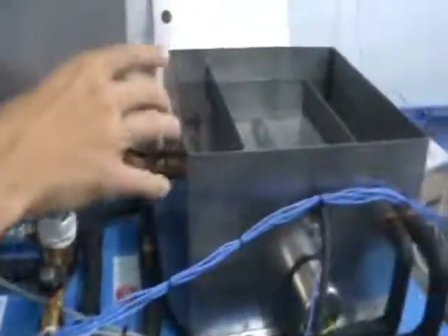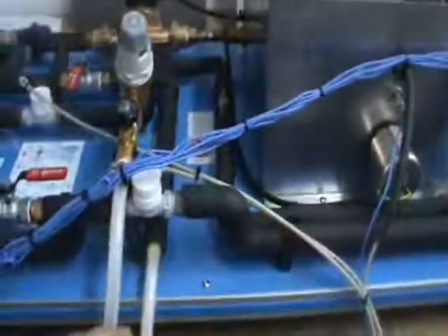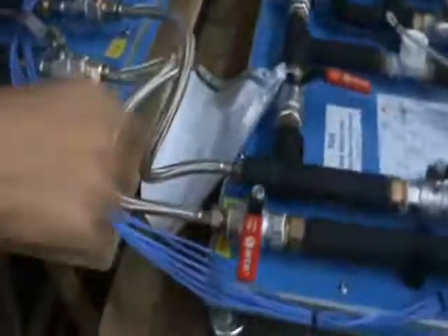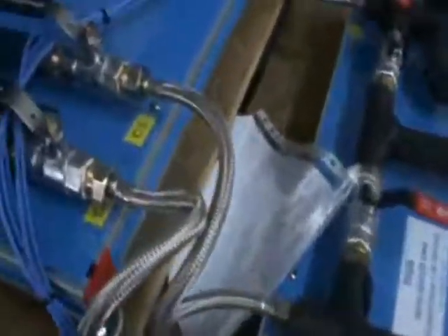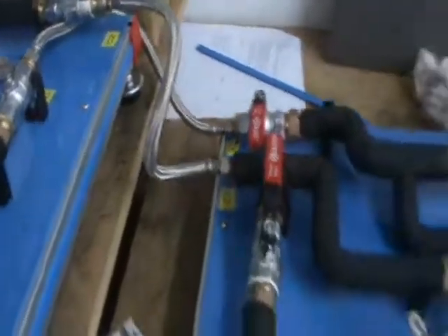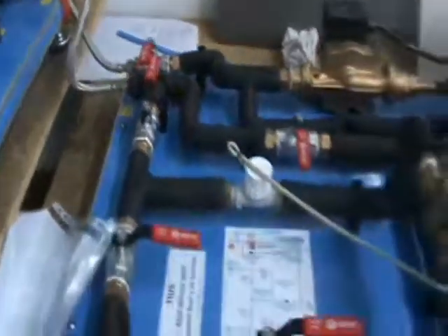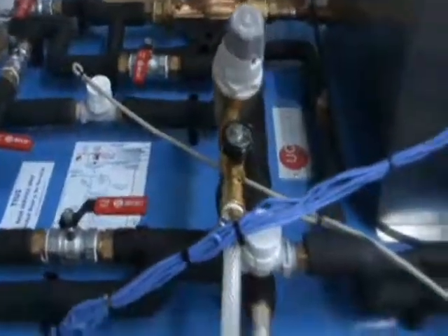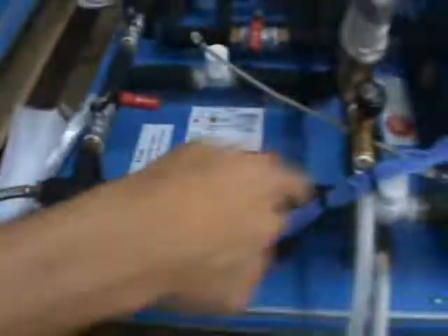Once we have filled up the tank and connected the refrigeration circuit to the tap, we connect the exchanger we want to work with, and open the proper valves depending on which way we are going to work, in parallel or in counter current. This is important.